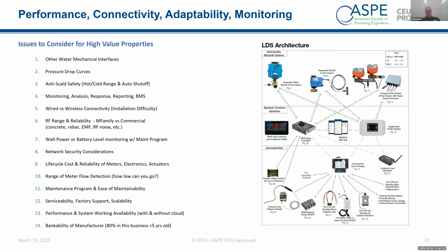All right. Some of these devices have solenoid valves. You're using solenoid valves for leak protection. If that solenoid is a normally open system and it takes power to close it, and you lose that power and that solenoid opens up, you've just exacerbated that leak, depending on the root cause of that.